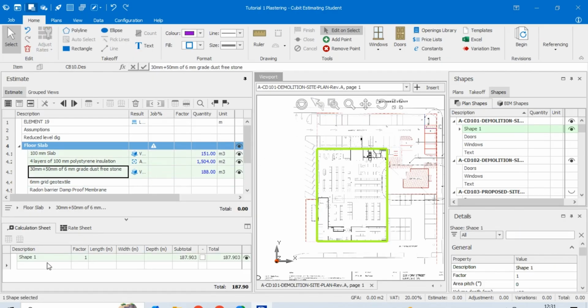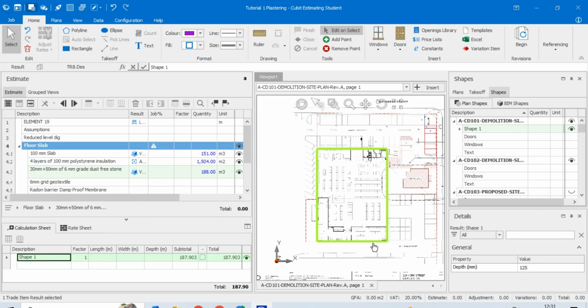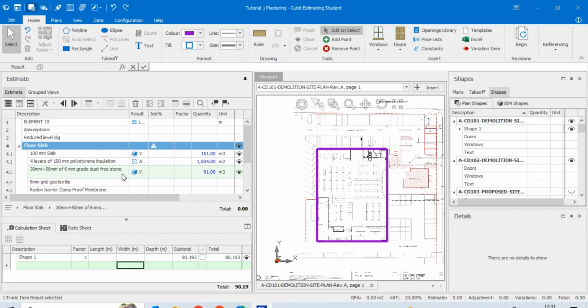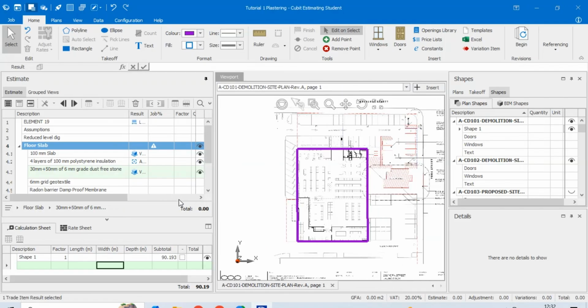So basically for the volume, you always have to confirm from your details the depth of either the slab or the columns or whatever you need to calculate the volume on. Then you change it when you select the shape, you just change the depth. Yeah, so you can also drag if you want to see a page better. You can drag according to how you wish it.